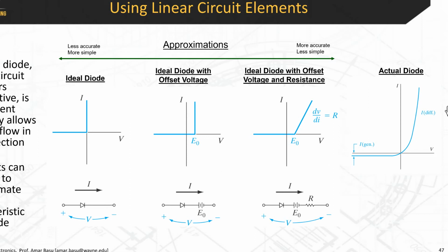So this is the actual equation that we're going for, the actual IV characteristic. One way, a very simple way you could approximate this curve, which is not ideal, well, pardon the pun, since this is the ideal diode equation, is to approximate this curve as just a flat line here and then a vertical line here. And that's what's being shown here. So the current is 0 when your voltage is negative, and then the current goes to infinity when the voltage is positive. So this is the representation of the ideal diode.